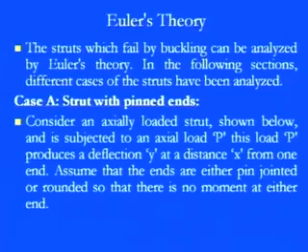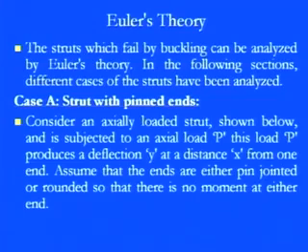Since the strut is always lying along the x-axis, whatever the deformations, the axis of the strut is always along the x-axis, and the deflection is measured along the y-axis, because both ends are pinned. When you apply the load, compressive or extension, whatever deflection comes is always in the perpendicular direction. So the deflection can be measured in the y-axis.